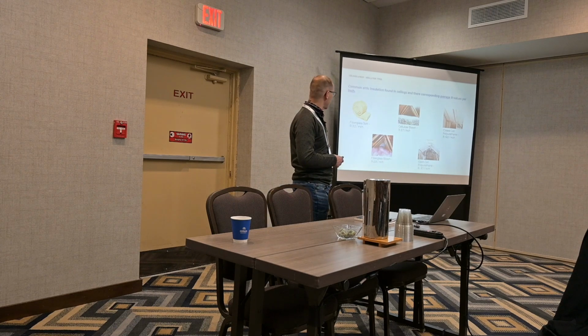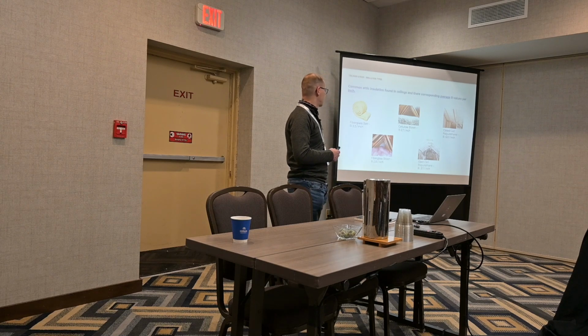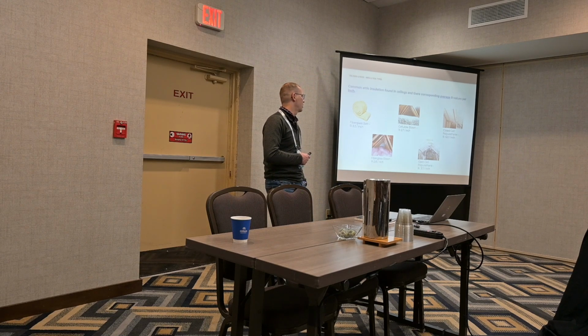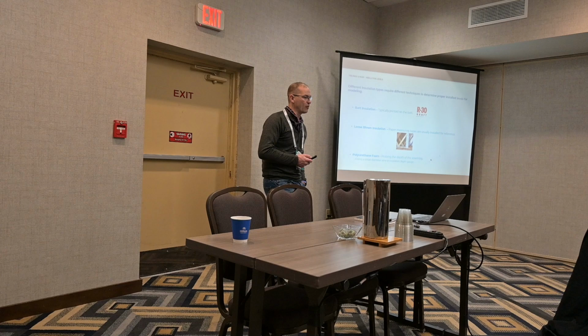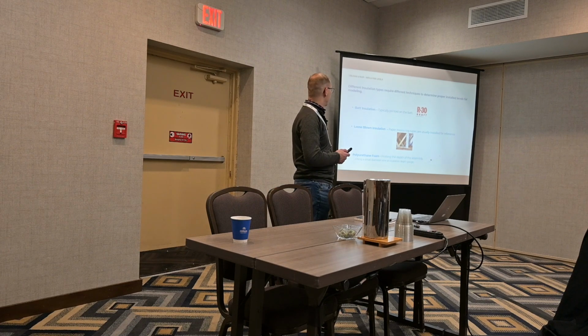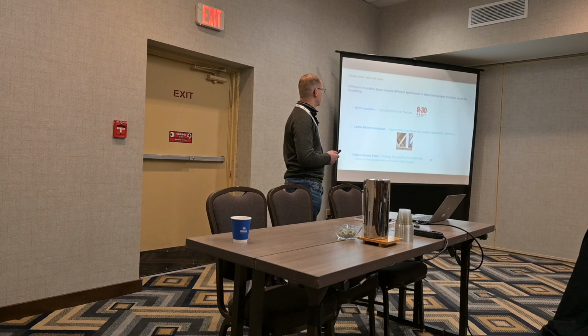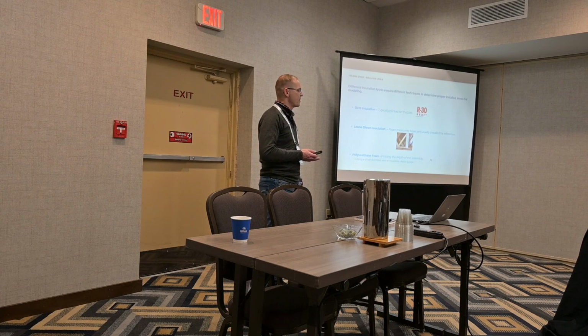Within attic space, common attic insulation, similar to the previous insulation slides that we did talk about, and with similar R values. Tips and tricks for insulation, different ways of measuring this. For batt insulation, typically you're going to see the R value printed on the batt itself, and you can look at it.